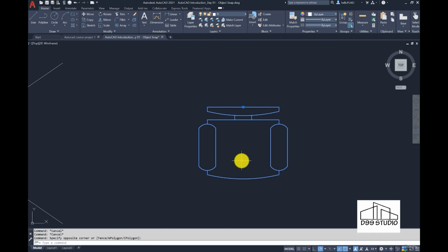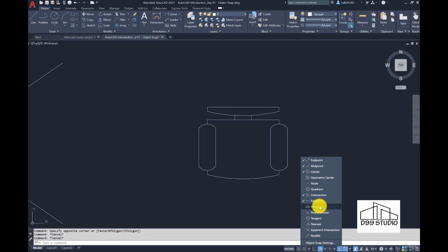So if we open up a new file, a new project, and we want that chair from that library, we will insert it in. But instead of that chair just being placed into the drawing at a random point, we use what is called an insertion point, which is this blue grip here. We will come down now and turn on the insertion.